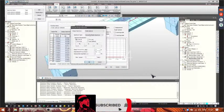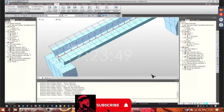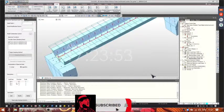Okay, the option is the same. Here we have to choose vertical design spectrum and use the same factors. Here is how it appears. We also define response spectrum load cases for the three directions of the seismic.